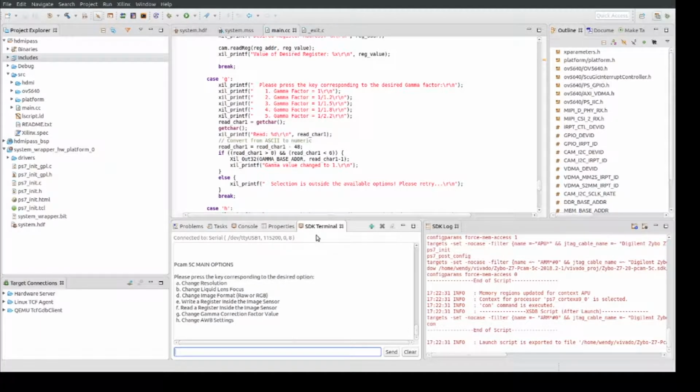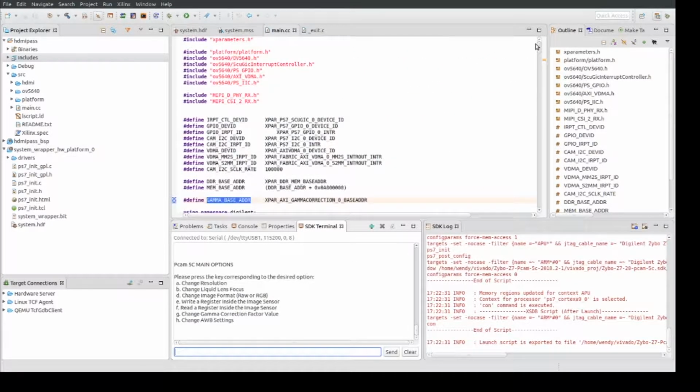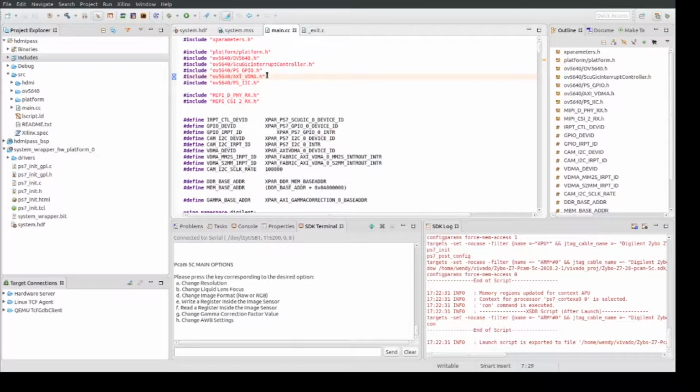But remember, it's out of date, so you need to tell it to not change anything when you bring it in Vivado. And the other thing you need to do is export the hardware and then import the actual code, this code. And to look at, some of this is their code that uses the actual Xilinx libraries. And again, I'll put a link to that. I mean, you can write your own